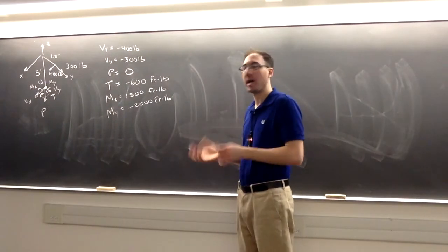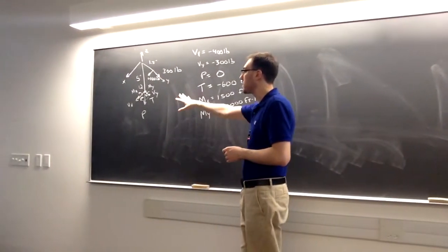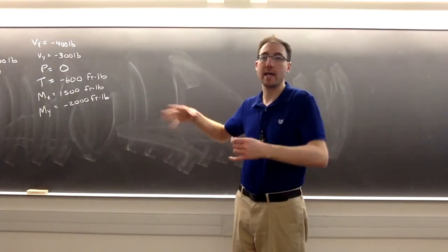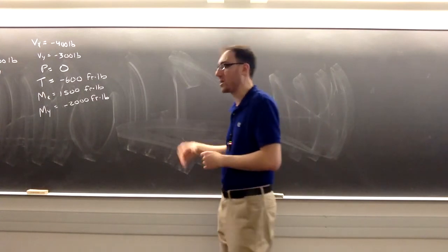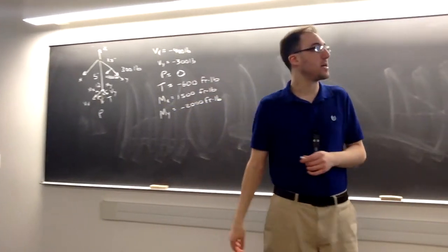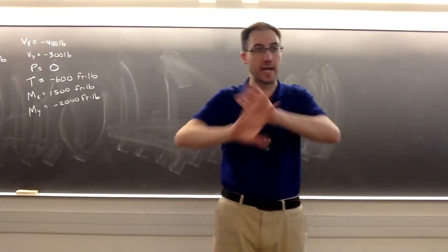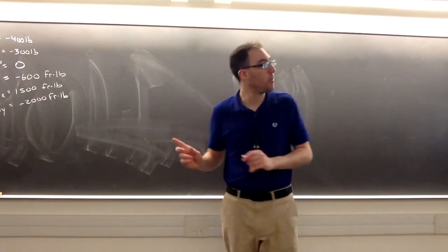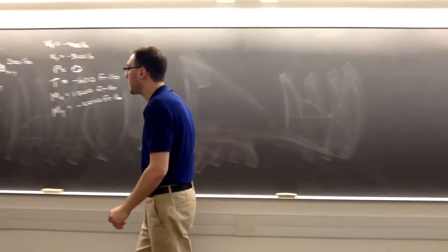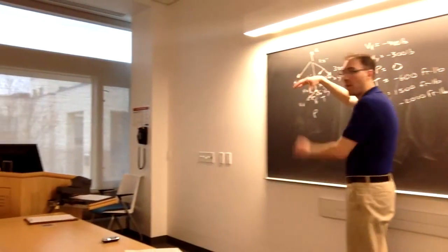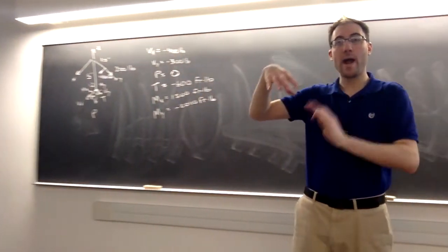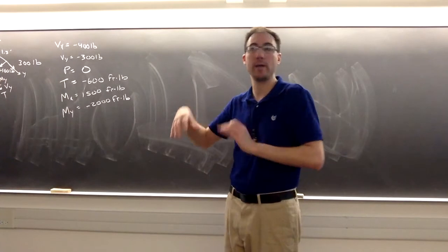We want to draw another picture so that we can see what our actual cross-section looks like, because in this picture, we didn't care if it was round or square. The loads don't care what the shape of this is. The stresses do. So I'm going to draw a second picture that looks at the cut surface. In this problem, we were looking at the stress state at A specifically. So I'm going to view it from the bottom where that cut is being taken, so I can see where the force is acting and what point I'm looking at.